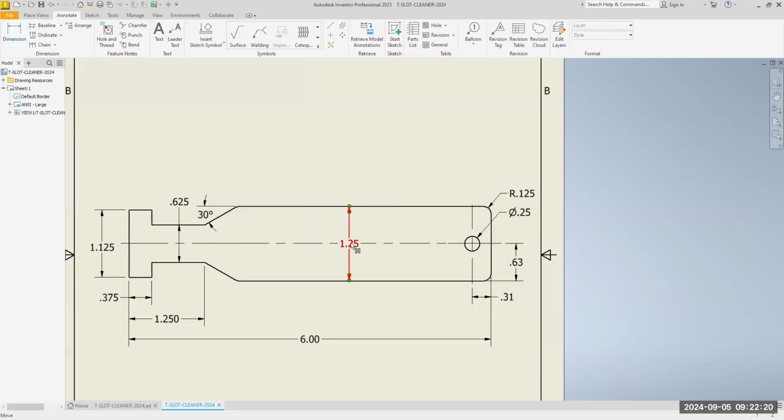Now, Mr. Morris doesn't want you to put the dimension on the part, so you can do this. All right. Now, we don't really need this dimension, but we'll talk about it more later because we have it right here. This is half into the center line. So we don't need this dimension, but this is what they call superfluous dimensioning, meaning more dimensions than required.